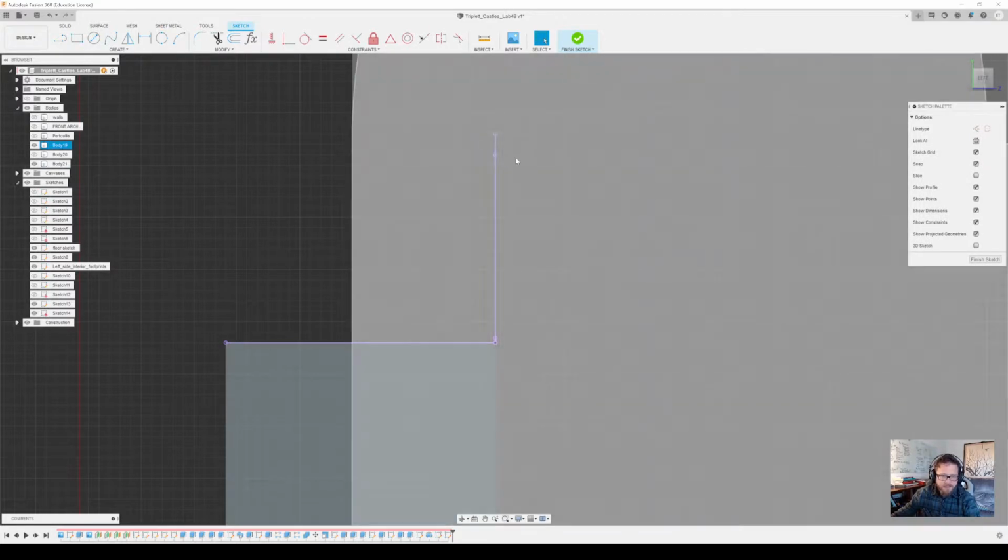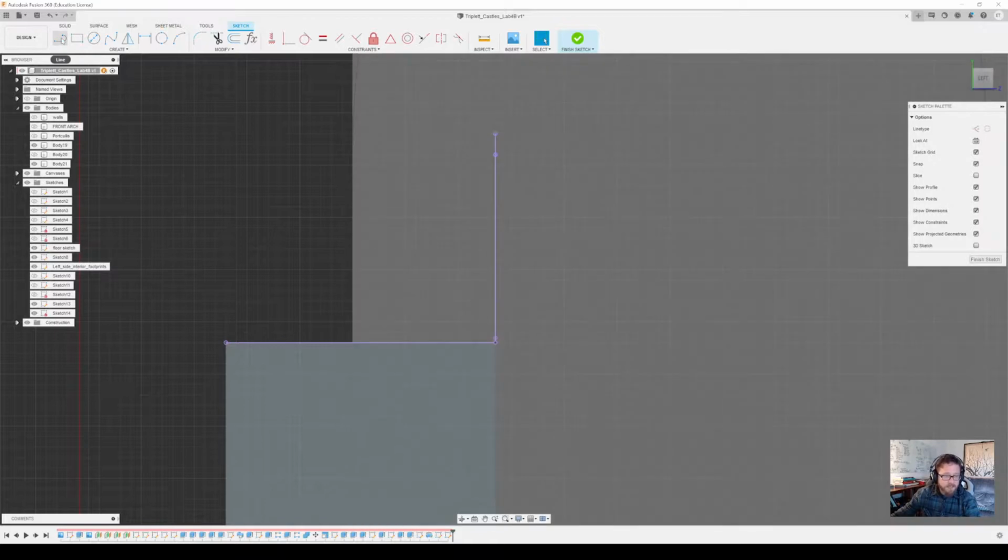We also have the height where this is going to merge. We've got everything that we need. I'm going to draw another line that is the height of this. Escape to clear that. Select it, hit X. I'll do another one down the middle. And that has to be the same height.